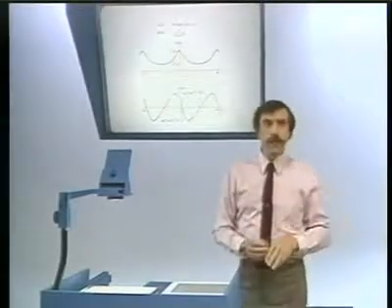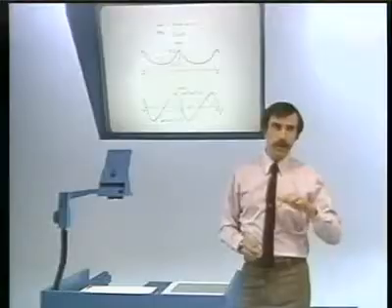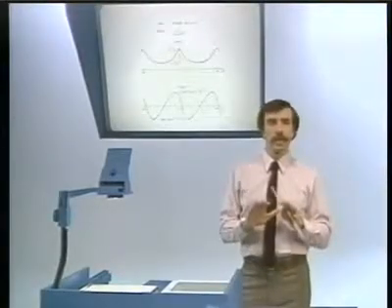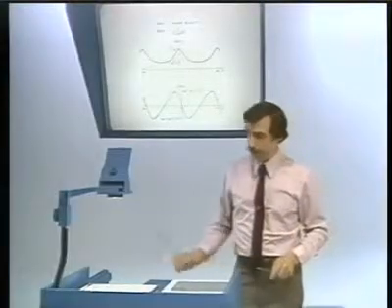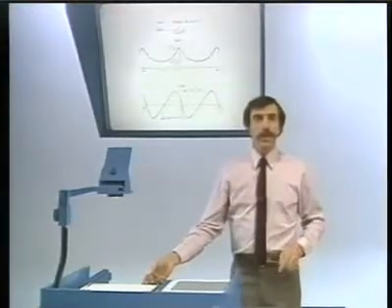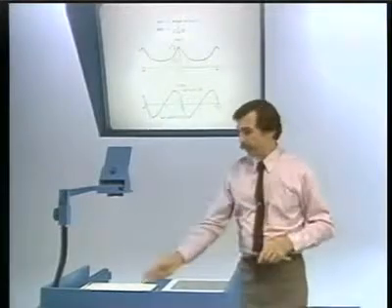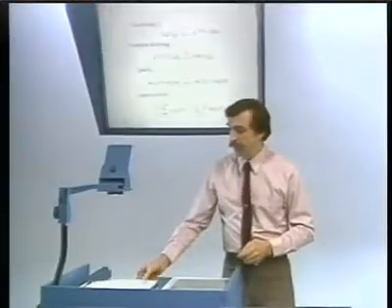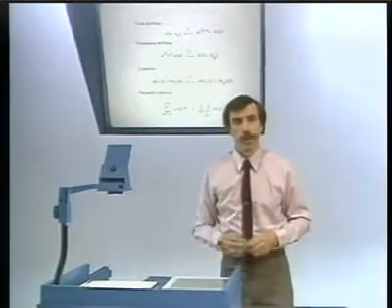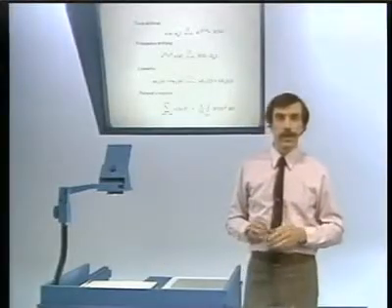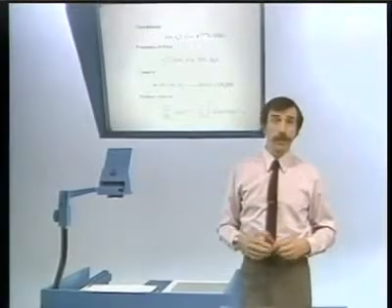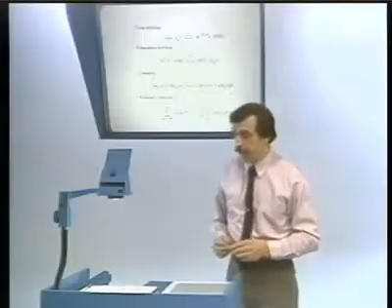We have this inherent periodicity in the Fourier transform, which I'm stressing very heavily because it forms the basic difference between continuous time and discrete time. In addition to these properties of the Fourier transform, there are a number of other properties that are particularly useful in the manipulation of the Fourier transform, and in fact, in using the Fourier transform to, for example, analyze systems represented by linear constant coefficient difference equations.